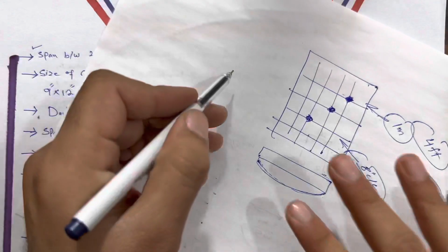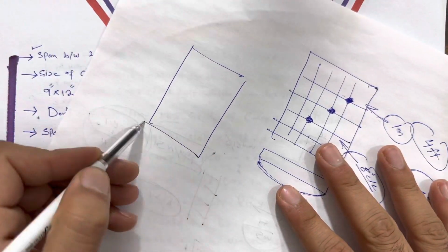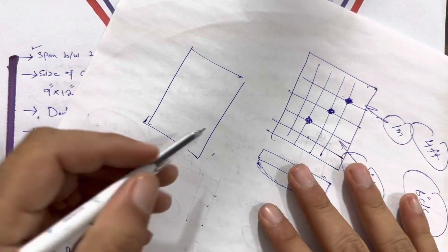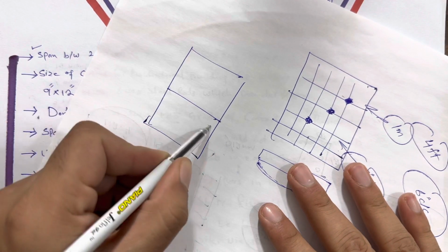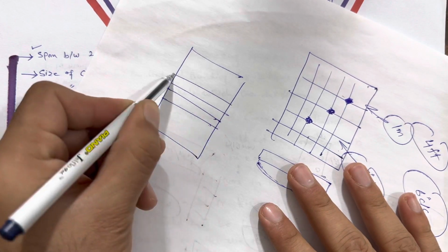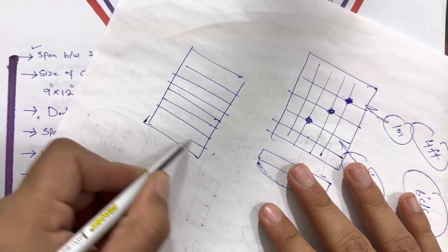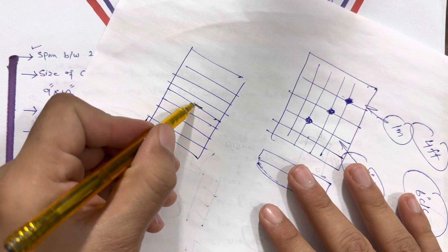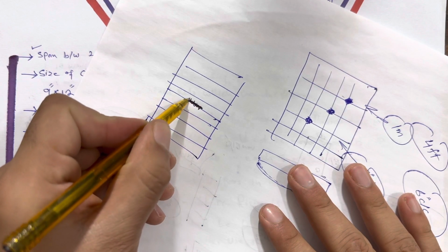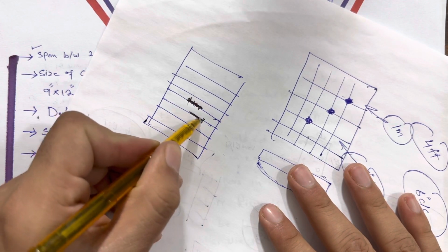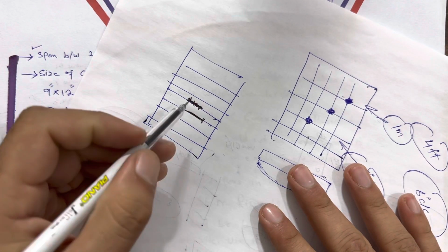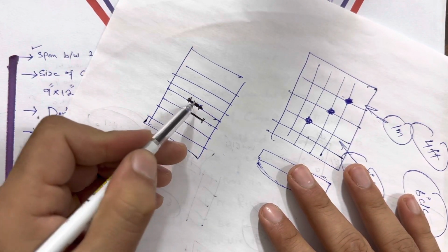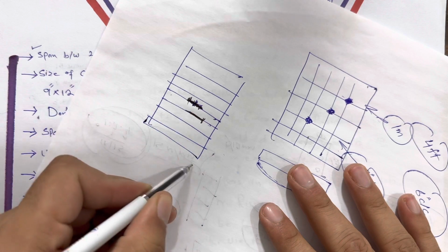As you can see guys, this is RCC slab, and here guys you can see we have the bars, main bars, our distribution bars. Why not on this side? So we are providing sometimes the lapping here like this. Here we are providing the lapping. So the lapping is not allowed here at the middle of the slab. That's why, because here we have positive bending moment.